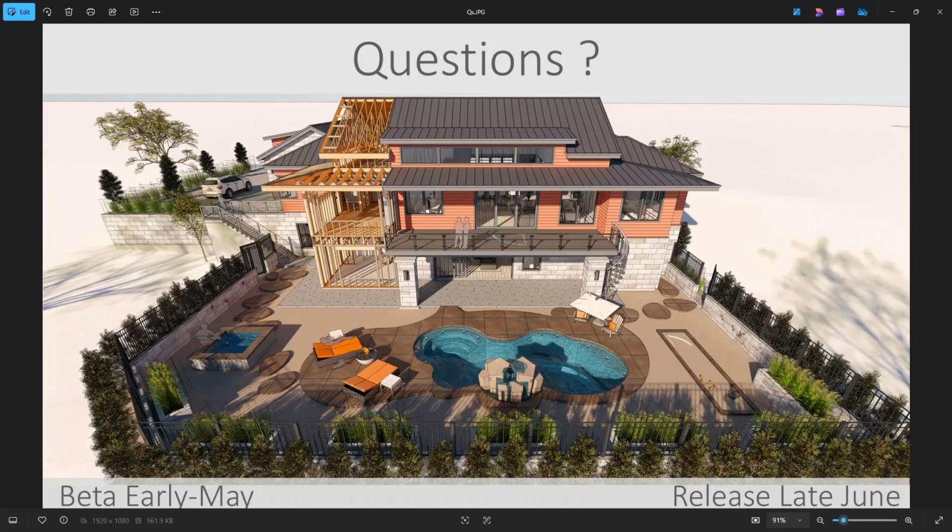I use a service here out of Missoula that gives me Recap files or LiDAR scans so I can build, and then I can take a section of that and create a PNG, and then import that so that I can put that on my section cut in Chief, and then verify that all my heights are correct. The thing is that PNGs haven't been transparent before.